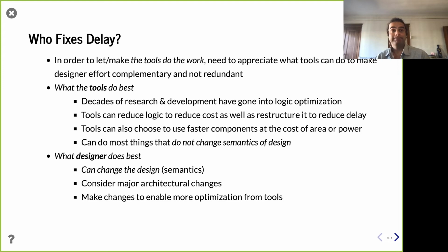A moment ago, I told you that paths that are shorter than the critical path delay are kind of invisible in a way, because they don't affect our timing, so we don't really worry about them. The tools are going to aggressively try to find those paths and, when possible, substitute those gates for gates that are slower but hopefully save energy or are smaller. And as long as it meets the timing delay, you're going to be happier, right? Your design is smaller and takes less power. Those are both good things.